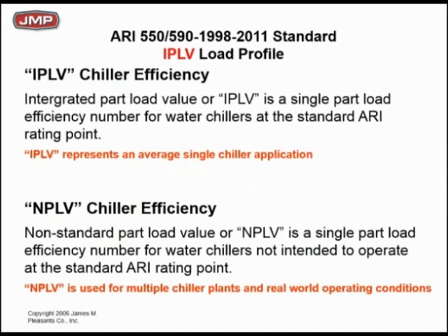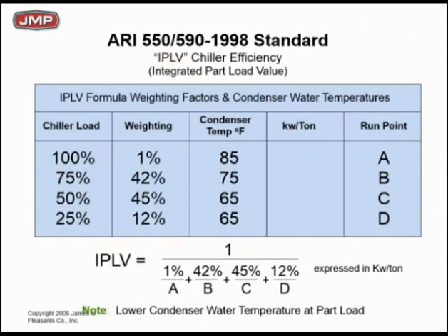In other words, if you don't want to use a standard IPLV load profile for loading up your chiller, which we'll look at in just a couple of minutes, and you know your load profile, so much the better. Let's go to the NPLV and load it in there, and you actually have the load profile for your project. In absence of knowing that, here is the IPLV load profile.